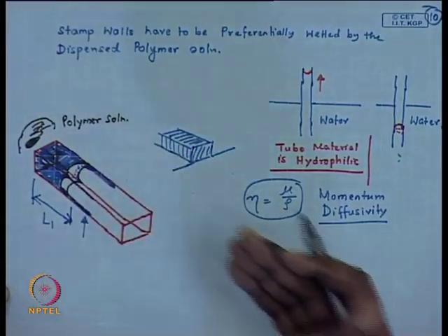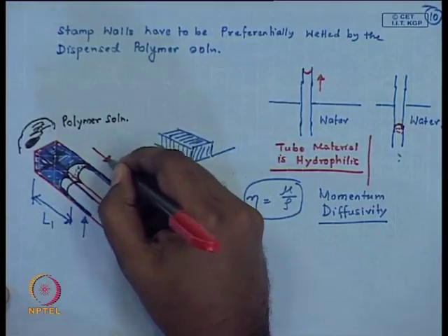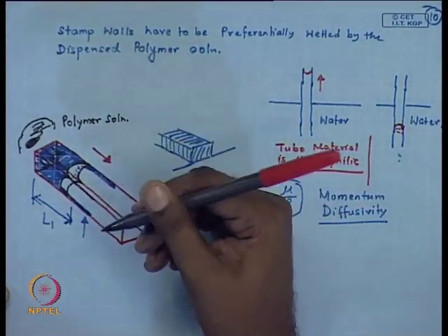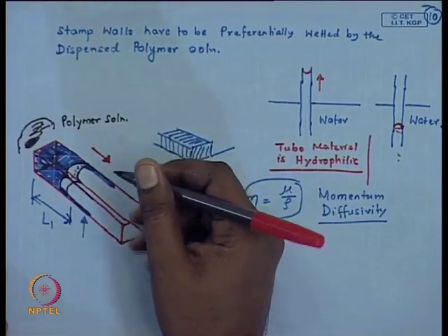So the capillary driving force over a very long length might not be adequate to sustain the complete filling, or in other words the dynamics at longer distances might become very sluggish. That might eventually prevent a proper pattern replication.